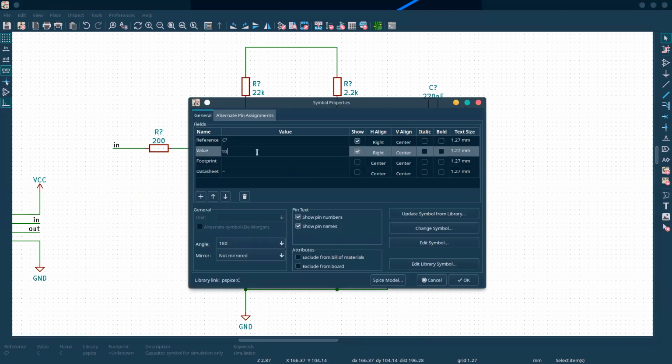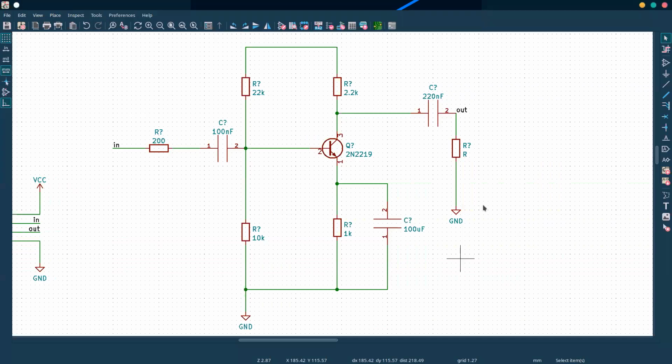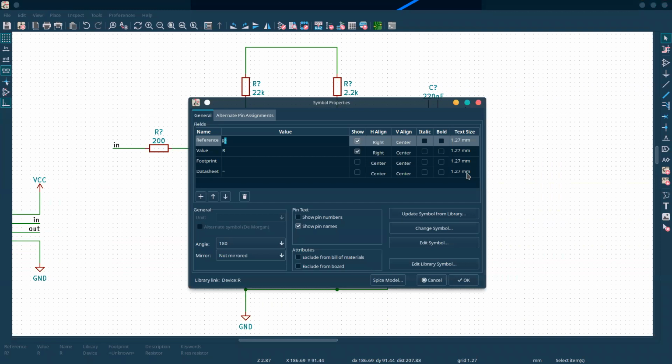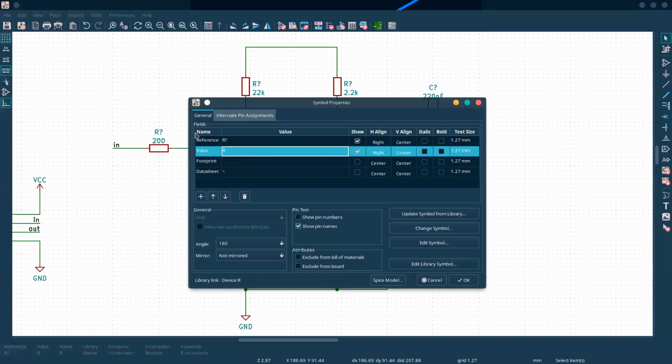One convention that's used quite a bit is, instead of 2.2K, you typically write 2K2. Or if it's 2.2 nanofarad, it'd be 2N2. Okay, I hadn't heard of that. What's the reasoning for that? Decimals are hard to write. Ah, print out a circuit, the dot is just tiny. Yes, that makes sense. It's also done for 3.3 volts, 3V3.